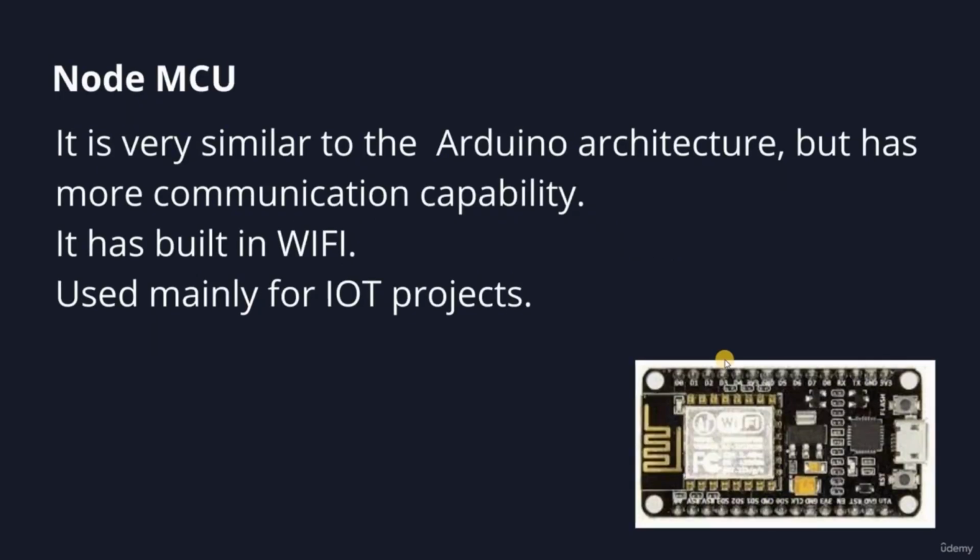The NodeMCU is very, very similar to the Arduino architecture, but it's a little bit more powerful in terms of RAM and flash, and it also contains a Wi-Fi module. It has a flash where you can write your program and let it execute, but it is mainly used for IoT projects. And we're going to get deeper into that later. I just want you to understand right now that NodeMCU and Arduino are very similar. The only difference is that it has Wi-Fi where you can communicate with other devices.